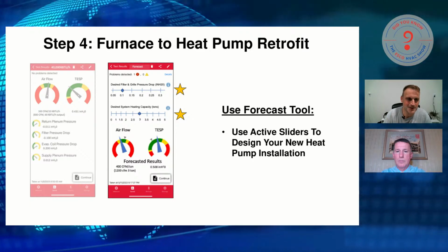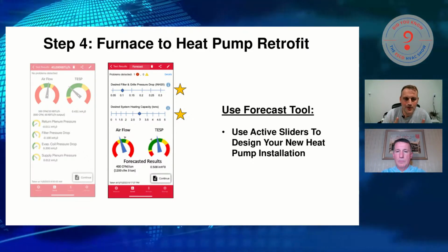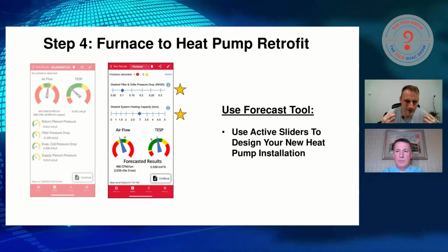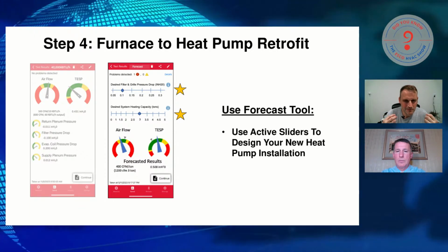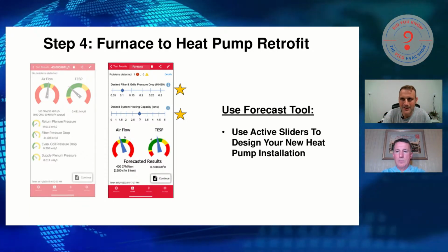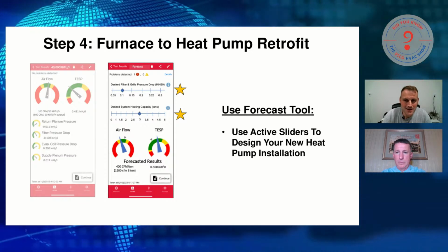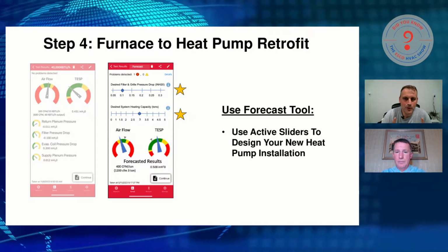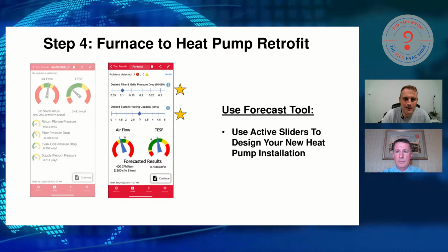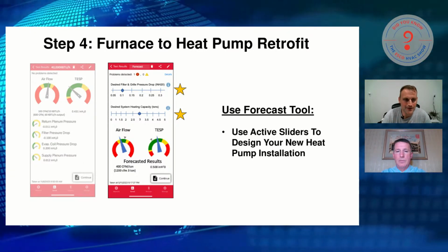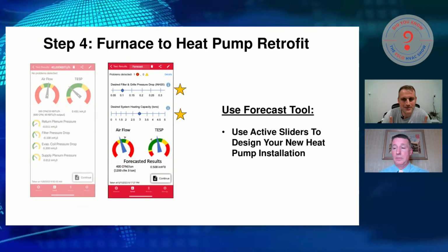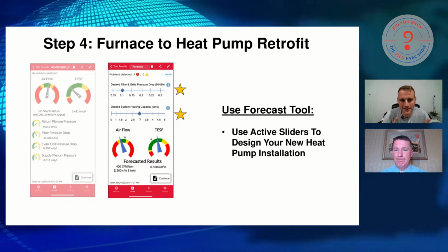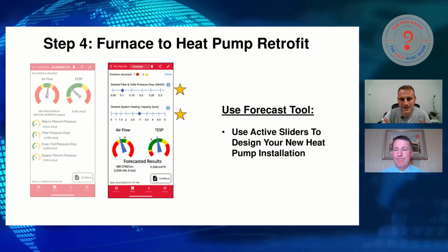Right? We've selected 3 tons for this. Sure. When you move those slider dials, you're essentially changing the components of the ductwork that are expected sometimes to be changed during a change out, retrofit, whatever you want to call it. When you move those, all the homework is being done for you on the dials below. So your airflow and your total external static pressure, those needles are going to move. That's why they're blue, right? Those are my active dials, and they're going to rotate.